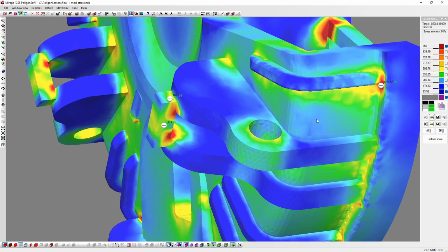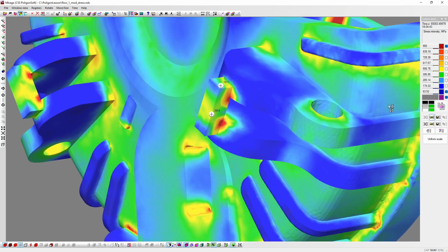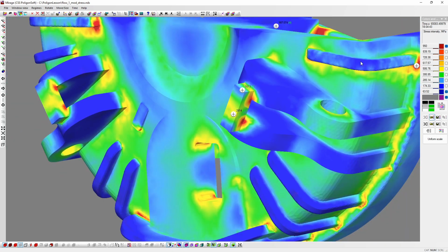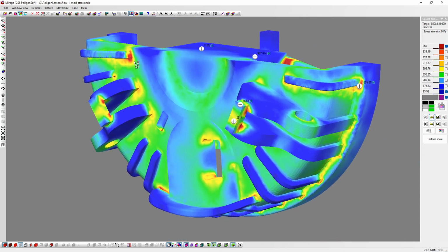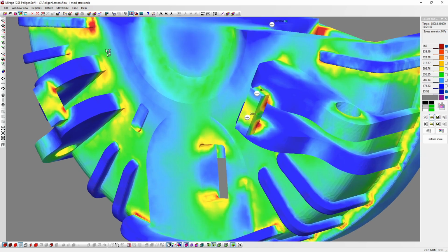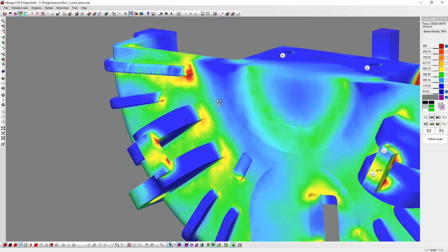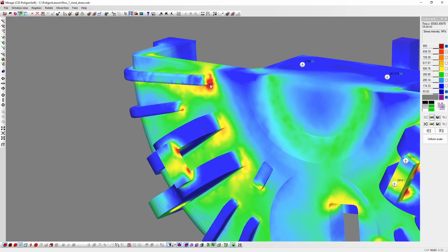It is not surprising that the maximum stresses occur in the gates, since the mold is rigid and the casting changes in size during the cooling process. It shrinks, since the sand prevents the free movement of the risers in the direction of the mold contraction. The maximum stresses arise precisely in them. Here, in the ribs, the situation is the same. The sand prevents the free sliding of this part, and a critical level of stresses also arises in this place.